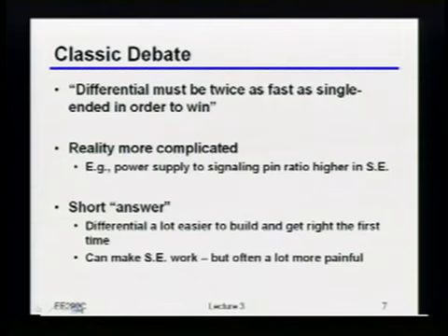And in particular, as we mentioned, the simultaneous switching output noise, or SSO noise, really does tend to cause you to have to use physically more pins, even for that single-ended signal. So typically you can only get away with maybe about 4 or 5 pins, even single-ended, before you'd have to put another ground there just to get a sufficiently low return path impedance. Okay? So that's where you start getting into these more philosophical arguments about, okay, is it really a factor of 2, or is it a factor of 1.5, what's the real number, and how much harder is it to get the single-ended thing versus the differential, right?